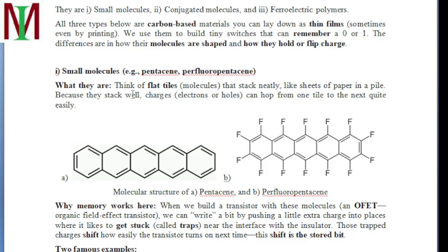There are many methods of preparing thin films: dip coating, spin coating, solvent evaporation, or even painting and printing. All these methods can easily be used in this type of semiconductor devices.